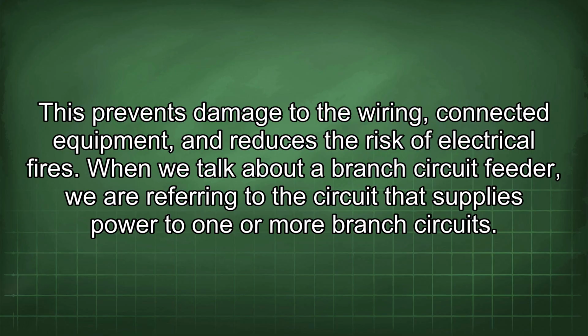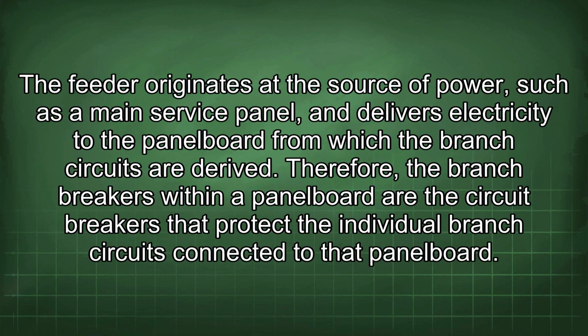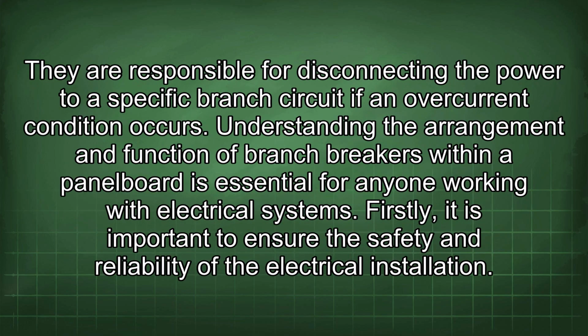When we talk about a branch circuit feeder, we are referring to the circuit that supplies power to one or more branch circuits. The feeder originates at the source of power, such as a main service panel, and delivers electricity to the panel board from which the branch circuits are derived. Therefore, the branch breakers within a panel board are the circuit breakers that protect the individual branch circuits connected to that panel board. They are responsible for disconnecting the power to a specific branch circuit if an overcurrent condition occurs.